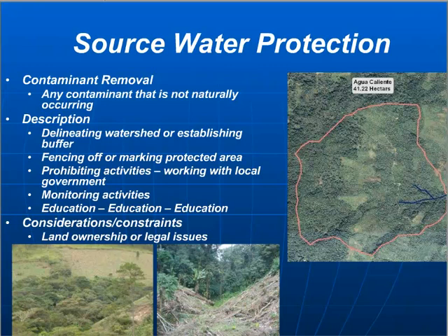And for our purposes, you know, really the first step is just figuring out what is the drainage area. Take some time to walk up and see the drainage area. I know I've been surprised a few times where I walk up to a source and it's this beautifully protected, you know, all these great trees. It looks perfect, and then you hike and it's just, gosh, sometimes the forest is so dense that you don't even see that 50 meters up gradient or 100 meters up gradient, it's completely deforested and it's used for agricultural fields where chemicals are being applied. And so it's important to just kind of walk up and get a sense for what's going on higher in the watershed.